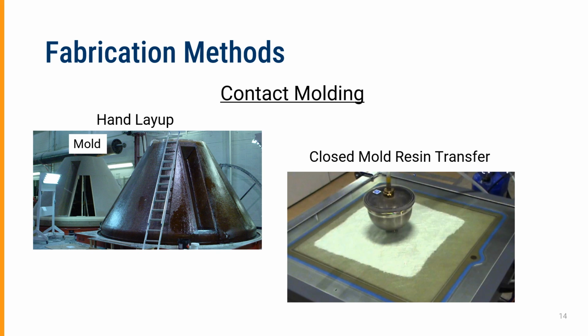The mold has been sealed and we're now drawing the resin in. This is actually a vacuum infusion process where the resin is coming in from the outer surfaces and it's being drawn in by pulling a vacuum up in this center tube, and so there's actually a wave front of liquid resin moving through the material to get there.